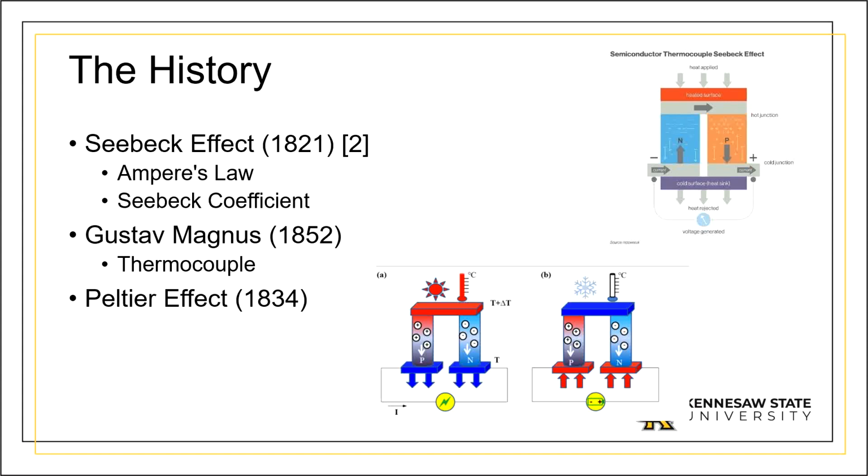After further testing, it was realized that a force, thermoelectric, was inducing an electrical current which by Ampere's law deflects the magnet. Seebeck figured out that the difference between the temperature between the two junctions produced an electrical potential voltage, which can force an electrical current in a closed circuit. The voltage produced is proportional to the difference in the temperature of the junctions.